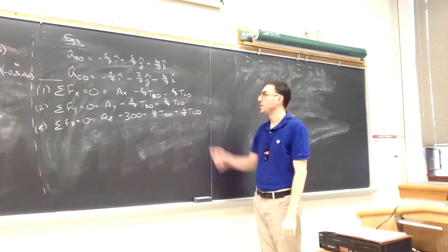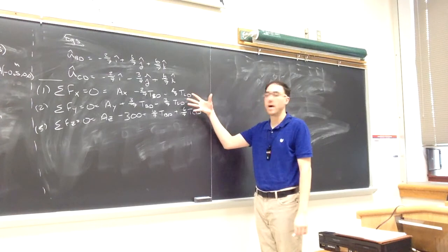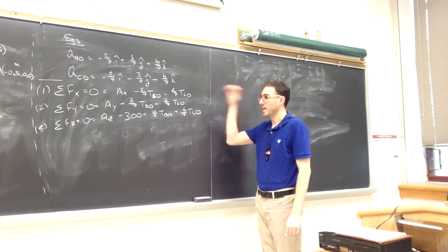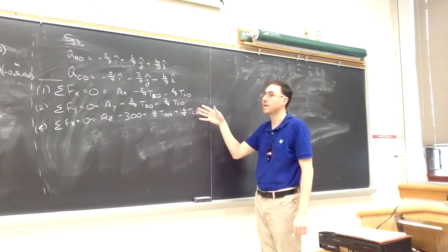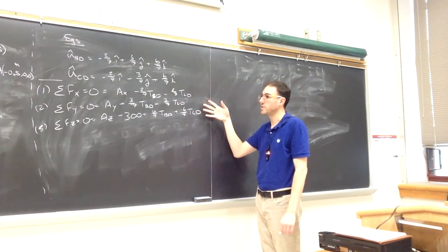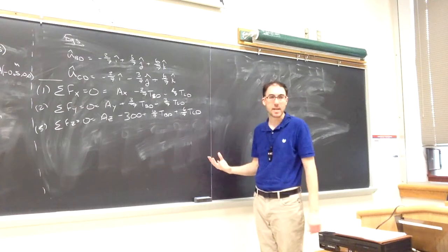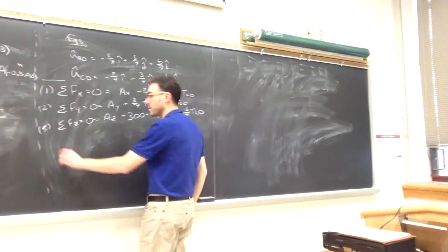In these three equations, I have all 5 of my unknowns present, so I can't easily use these yet in order to solve for any of the unknowns. So the force equations are done, but at least immediately, they're not too useful yet.